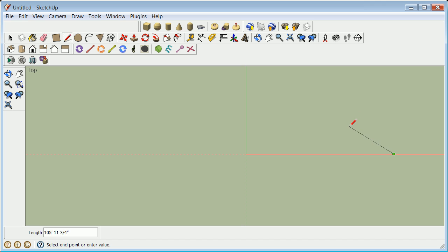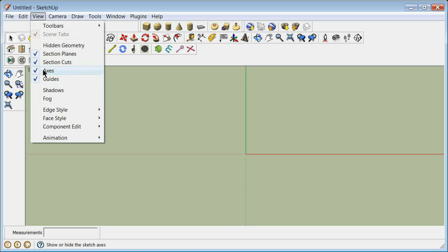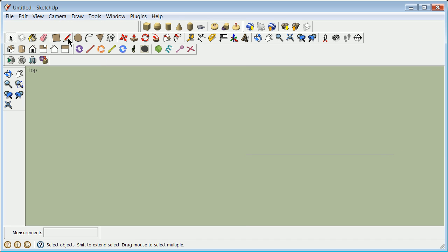That's fine. I have to then click that, hit escape, click on that, right click, erase. I can now turn off my axes so you can see that better. Now I'm going to go, once again, 300 up. I click on it. I could just type in 300 here, but I want to get used to relative coordinates. So I'm going to go 0 feet, comma, 300 feet, comma, 0 feet. Now I finish out, hit escape, click, select, and out, because I really don't know how to finish out a command that well here.